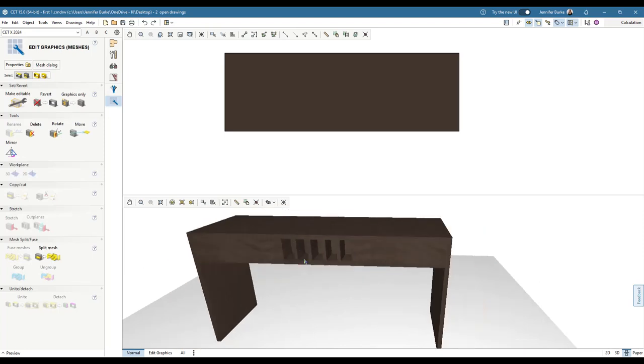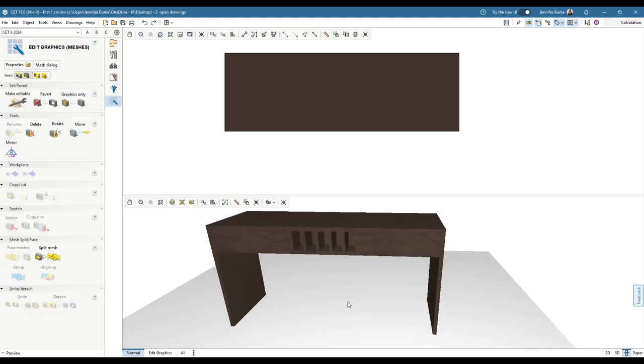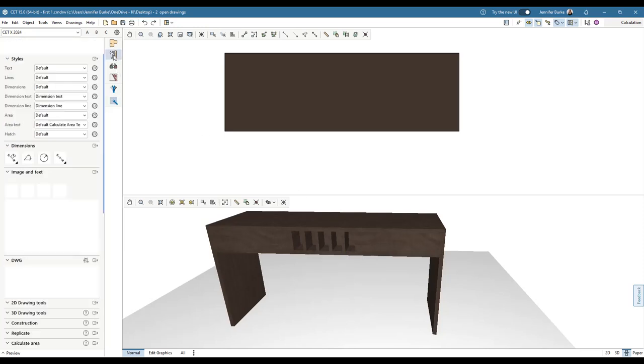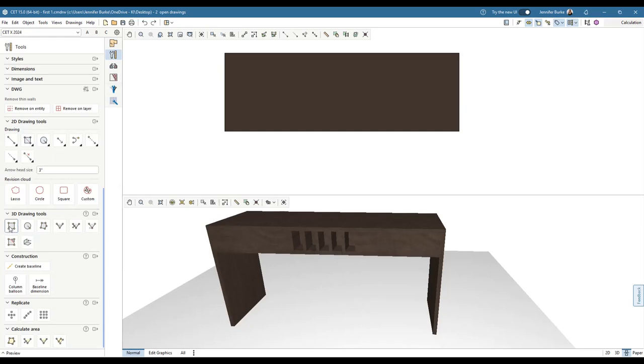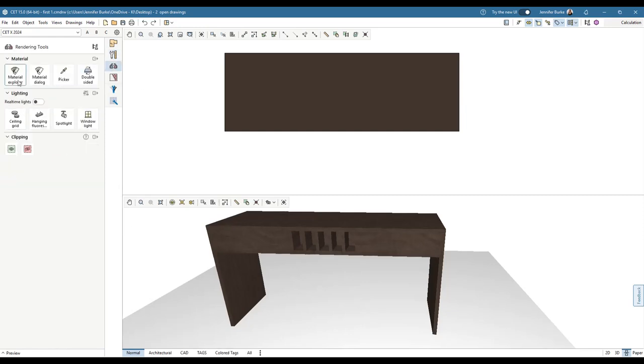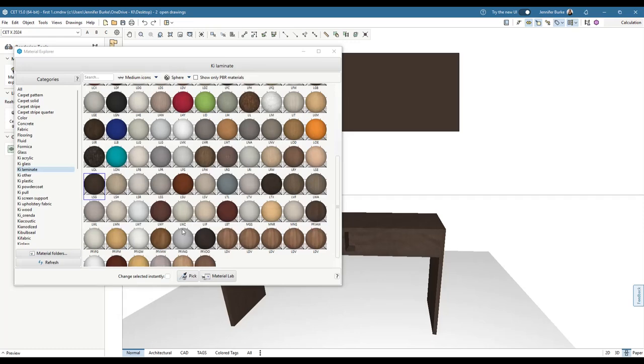To avoid that, you could not use the subtract. So the issue with that is having that solid and having those additional solids subtracting from the main event there. You could just use a bunch of different rectangles to create your slots, and then the grain direction will go correctly, apply correctly I should say. Or maybe depending on the type of finish, maybe you're just going to be doing a white or a different solid, that sort of thing.